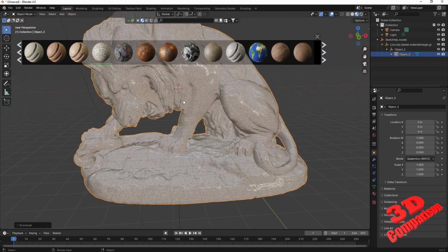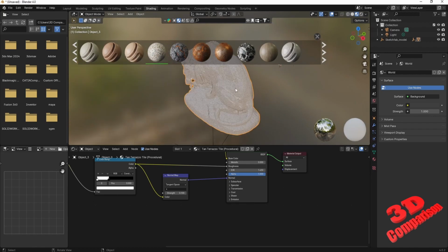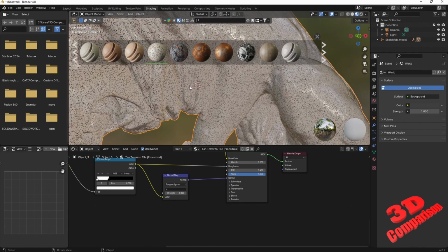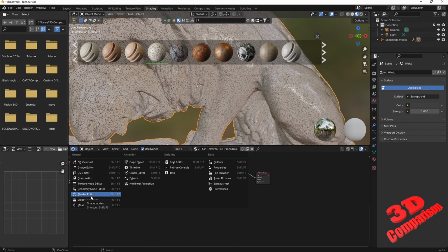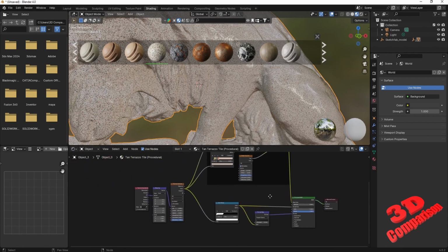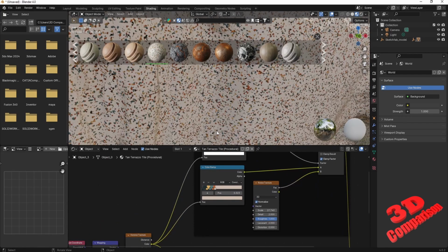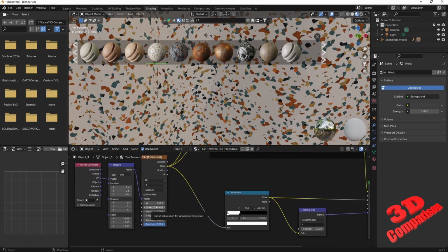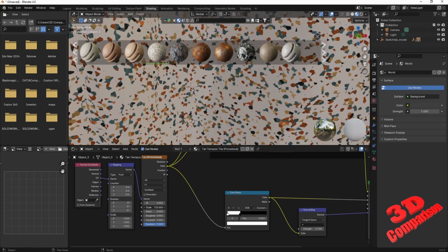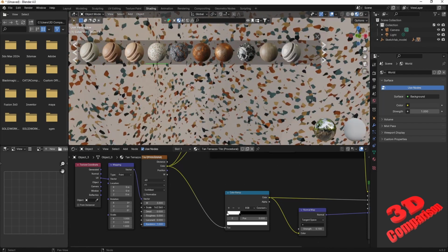If you wanna change the scale of that, we just need to go to the shading within Blender. Over here you can press again on numpad on the comma button to zoom to the selected element. And at the bottom within the shading editor, this will be open by default, we will have the possibility to change the scale. So we have the color ramp over here where we add those color elements, and we need to change the scale value over here. So I can drag and drop this, so I can just move it to the left and to the right, and that will change that scale.